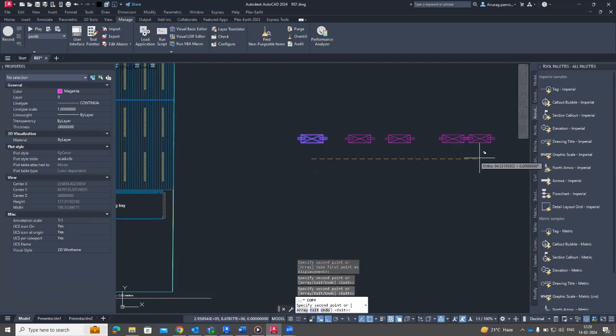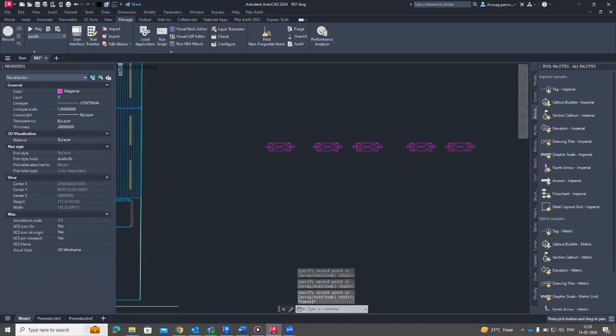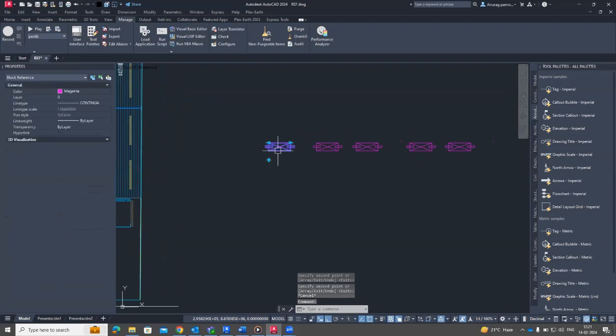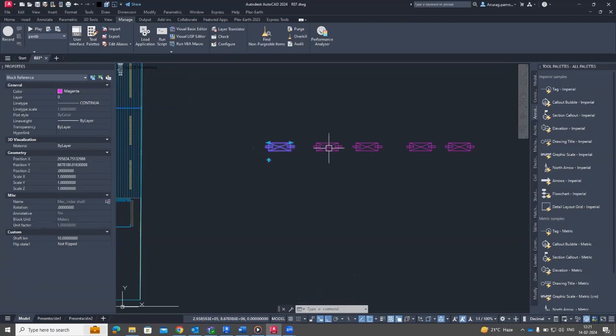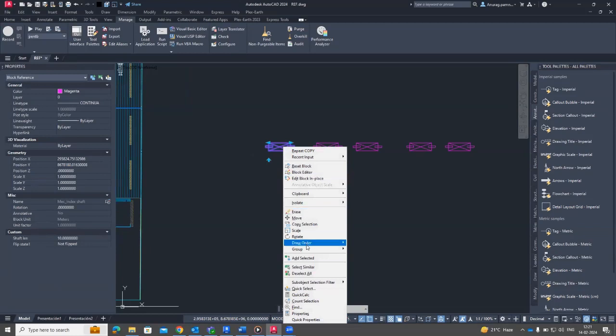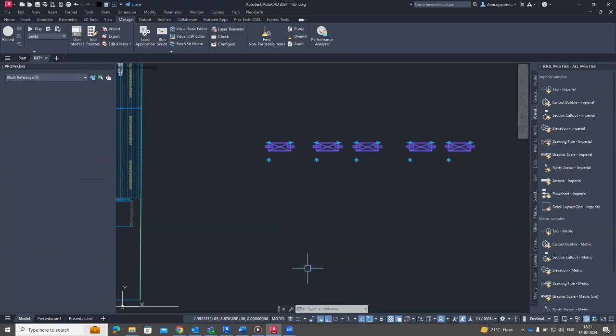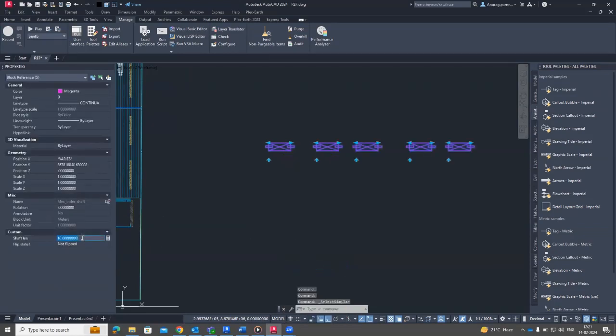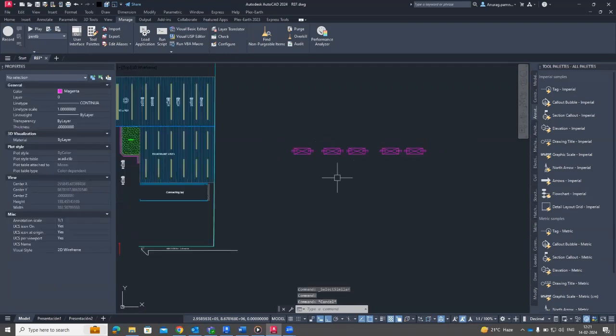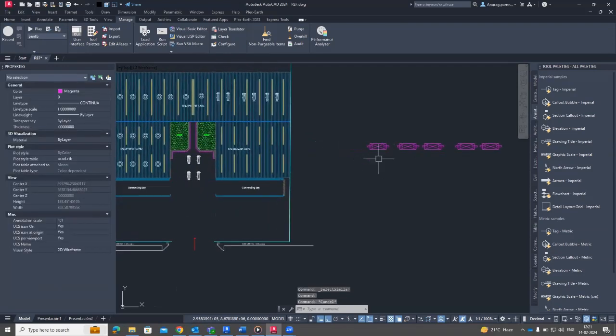And if I make certain copies of it, CO. So this is how, for example, I'm making now, okay, 5 of the copies. So I can instantly change those parameters from my left-hand box. Okay, that is the shaft length you can see. But if I need all of them to be replaced with the same length at once, what I will be doing is right-clicking on it, select similar. All of these are selected. Now I can change my height to 5 or 8, likewise 15, say. Let's do it for 12. Okay, you can see everything has been changed and scaled according to 12 as a shaft length.